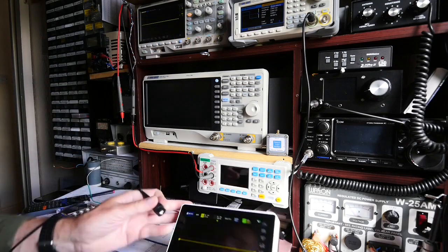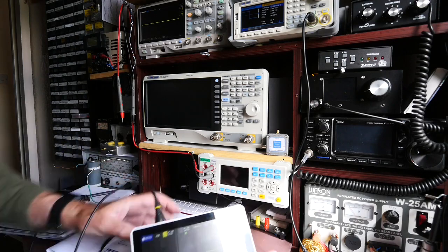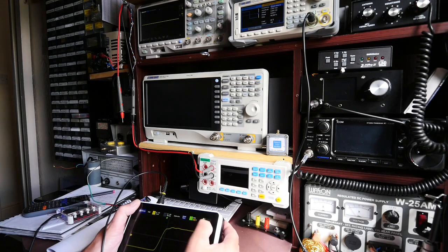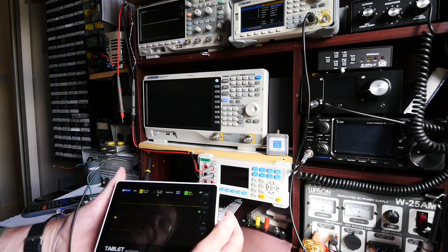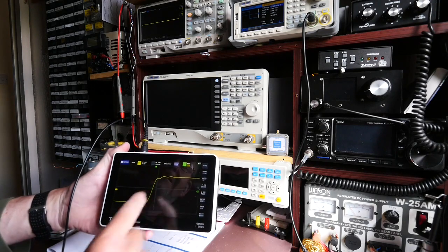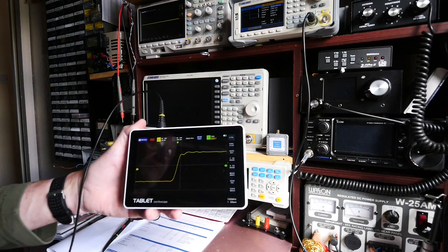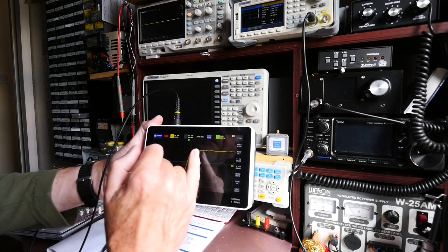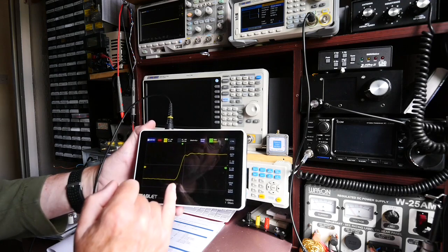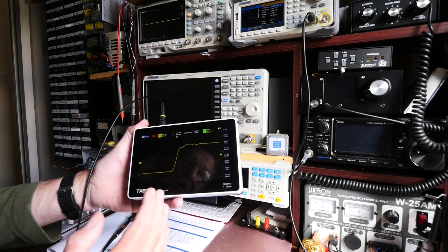So we're saying about 3.72 nanoseconds. Let's see what the tablet scope makes of that very fast rise time. I'm going to have to just change the vertical scale because it doesn't output quite so much. And again, struggling to trigger, but you get the general idea here. If I just pause that so we don't have the signal jumping about. Again, we've got about 10 nanoseconds, something like that. We've got about a division between the 10 and the 90% point, so it's pretty much the same.